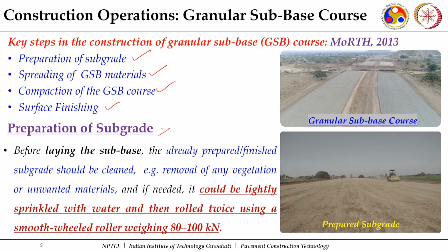So, under the aspect of preparation of subgrade, the important part is that before laying the sub-base course, the already prepared finished subgrade should be cleaned, because there may be some amount of delay between the preparation of the subgrade top and when the construction of your granular sub-base course has started. During that delay, some changes may have happened: it may be a rainy season, some vegetation may have grown up, or there may have been uncontrolled movement of vehicles which may have loosened the topsoil.